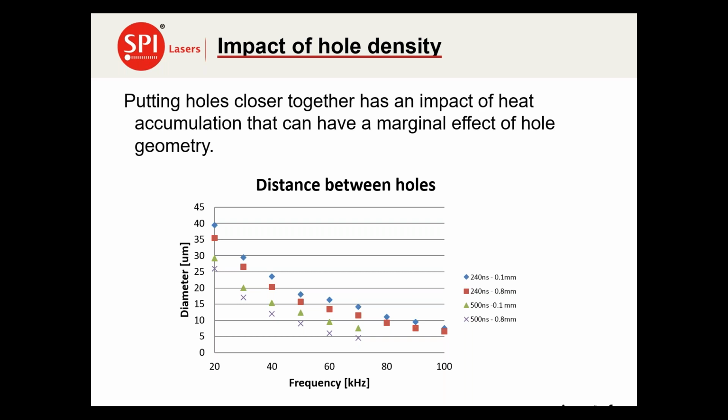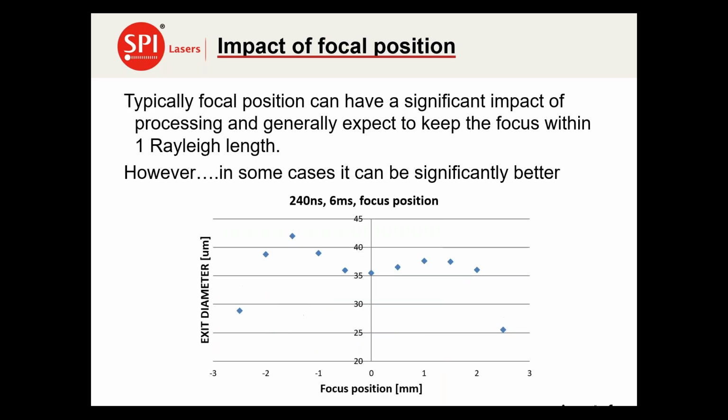The density of the holes can also have an effect, because what you end up having is heat accumulation, and heat accumulation can actually impact the amount of energy that's available and the dynamics of the process itself. So it's something that you need to be careful of. If you go too close, you slightly enlarge the holes and actually create more problems, more debris as well. So it's something to be careful of.